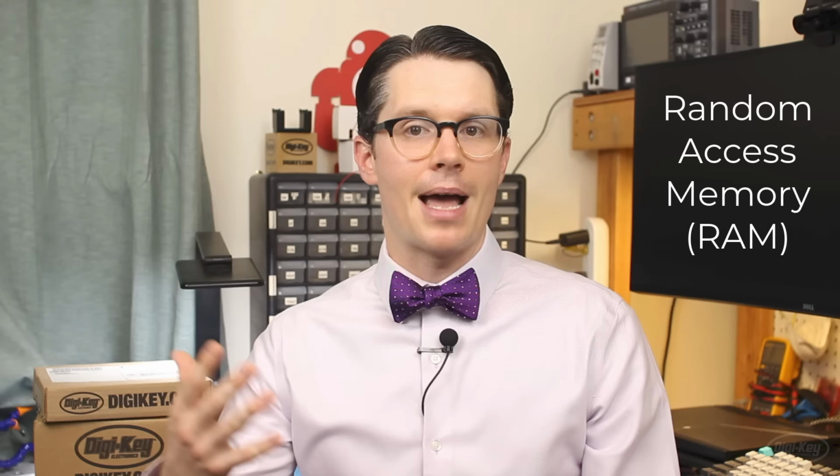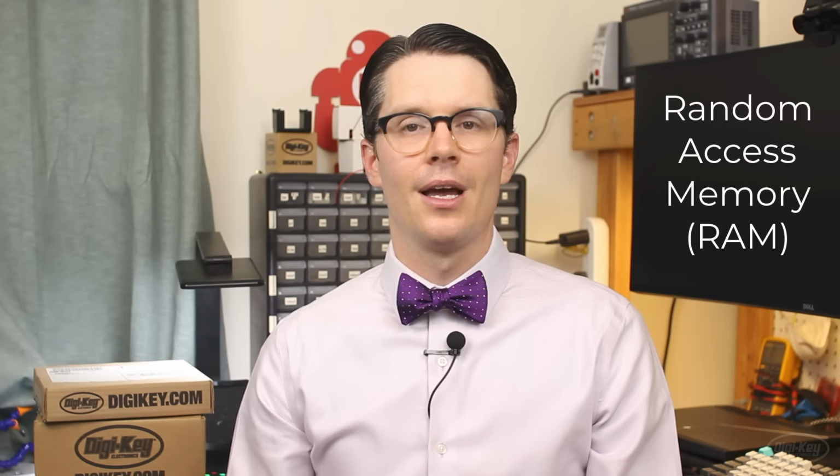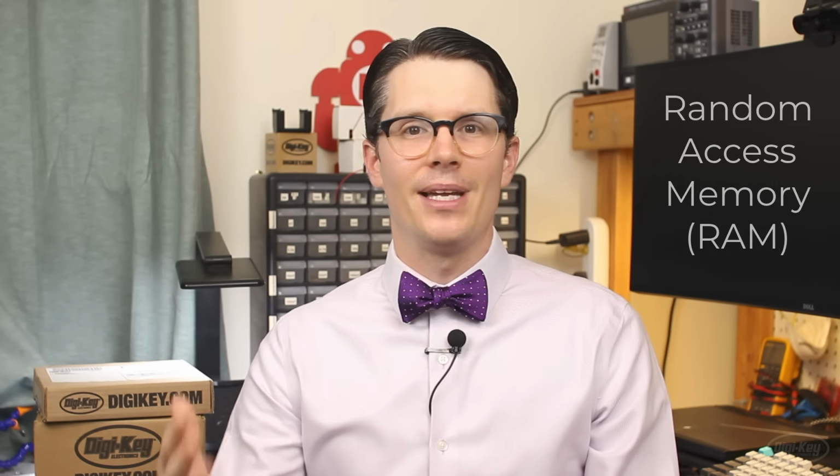Being able to store data is incredibly useful. You could, for example, take the D flip-flops that are in your logic cells and combine them in such a way to create a short-term memory solution inside your FPGA. However, if you need to store even a few hundred bytes of data, that would very quickly consume a lot of your logic cells. So most FPGAs offer a form of block RAM to give you some access to storage elements. Let's see how to use that block RAM in Verilog.